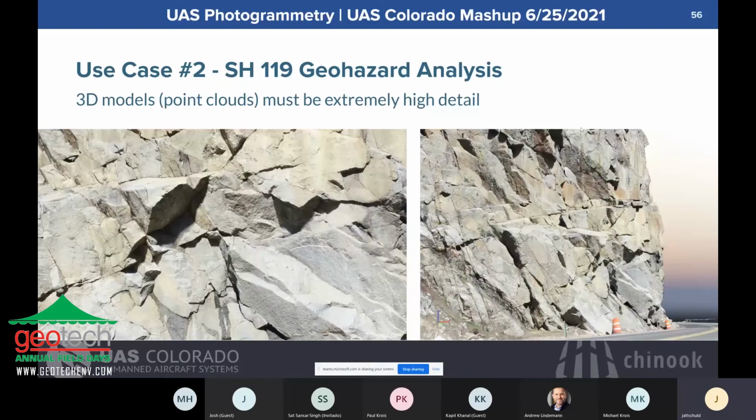If you're getting enough good photos that the software can pick out the points to tie together, especially if you're combining it with some ground control or even RTK GPS on any of the units, so you get really good positioning on where the drone or camera is, you can vary that more. So you want to stay fairly consistent, but you don't have to hold to it exactly, if that makes sense.